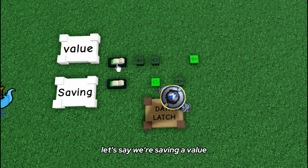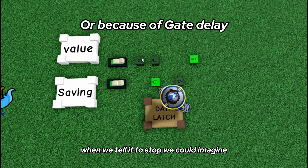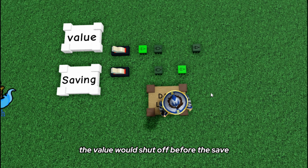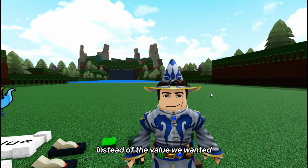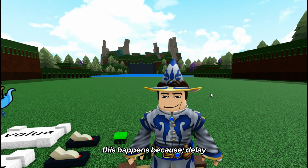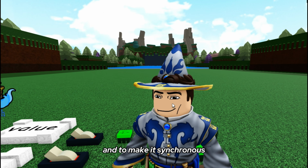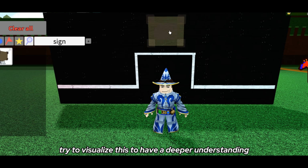Let's say we're saving a value, and then all of a sudden, due to some form of delay, when we tell it to stop, we could imagine the value would shut off before the save, ultimately making the value turn into a 0 instead of the value we wanted. This happens because, for one, delay, and also because the circuit's asynchronous. And to make it synchronous, we're going to have to introduce something called the clock. Let's try to visualize this to have a deeper understanding.